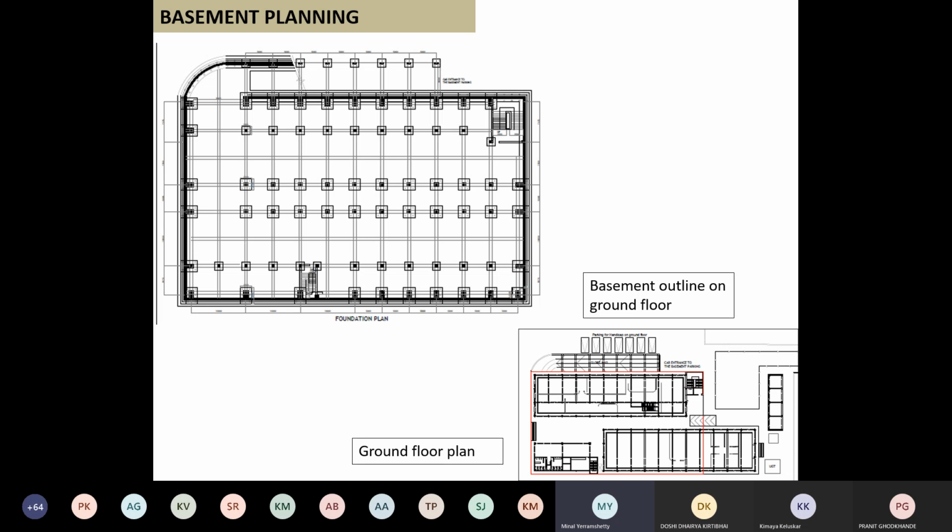I will not allow you to go for 70 meters, 80 meters, pointless sir. Now somebody will say, but what if with the new technology there are great fans available? Great, go ahead. But you know what? When you have this kind of a throwing capacity, they make a lot of sound. Now if the technology is giving you a soundless fan, fantastic, then we can go ahead. But right now, for the academic purpose, we will take 40 meters as the max.